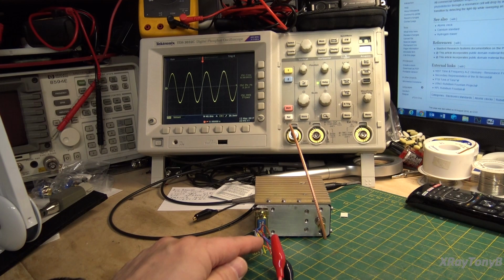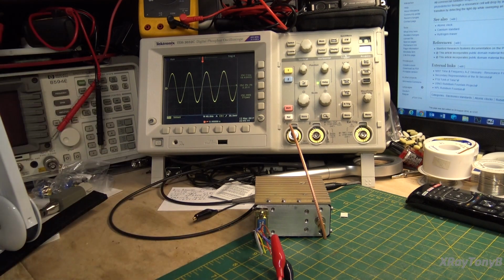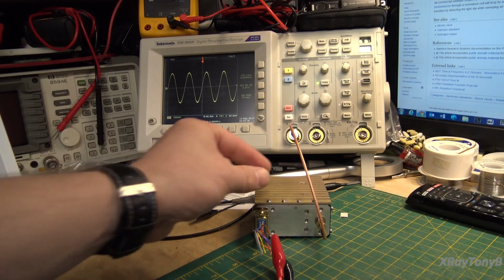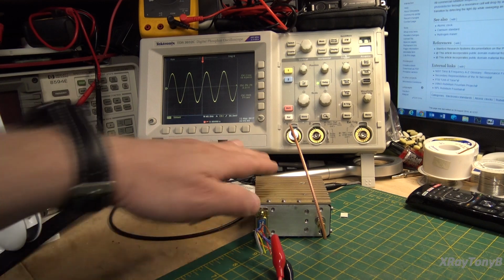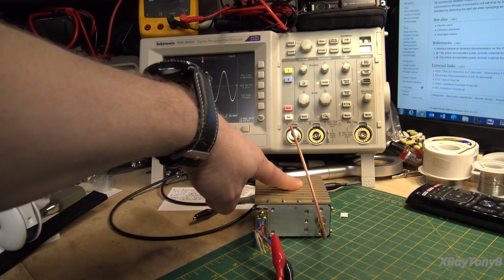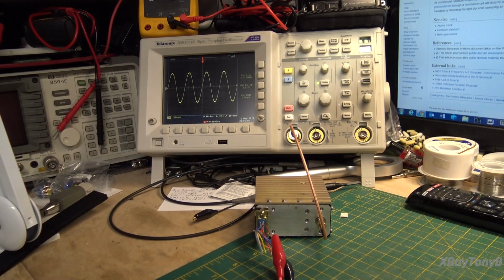And one of these lines here is just an active low signal that you can connect to an LED, and that's called your lock signal. Once the oscillator has reached its ambient temperature and has locked in on its pre-configured frequency, it'll pull that line low as an indicator that it's locked. So normally you'd put a little LED there, and when the LED comes on, you know that this thing is warmed up and locked in on its preset frequency, in this case 10 megahertz.